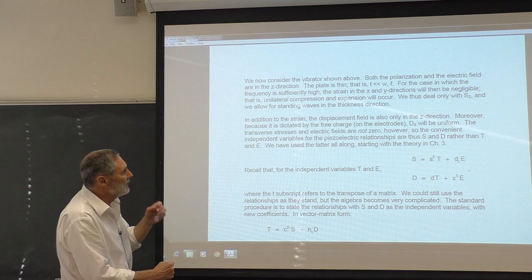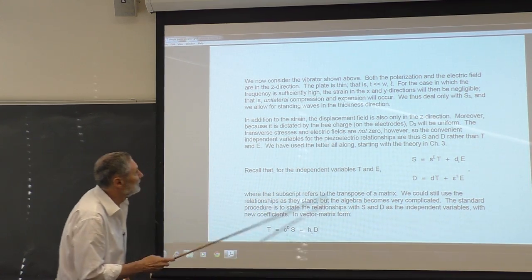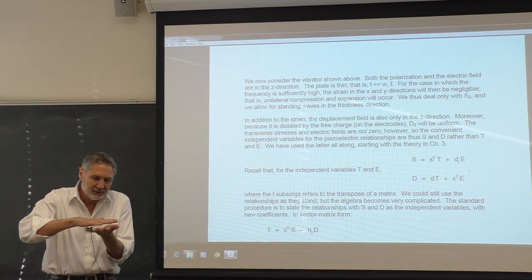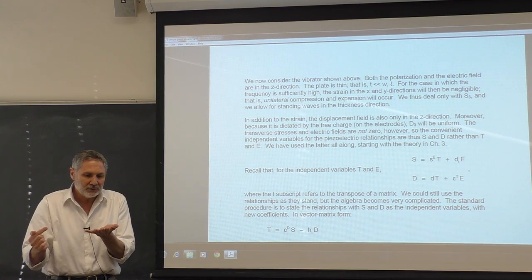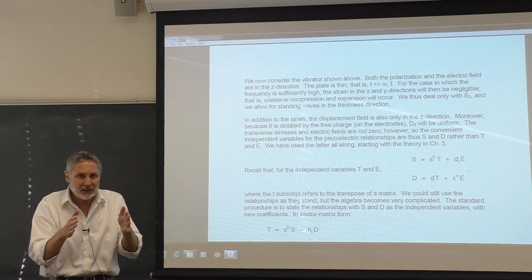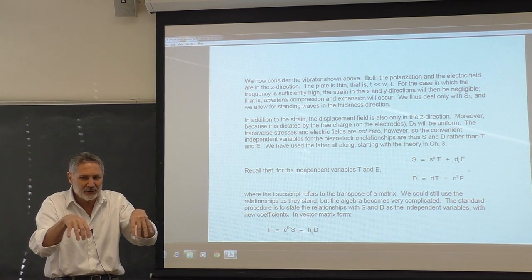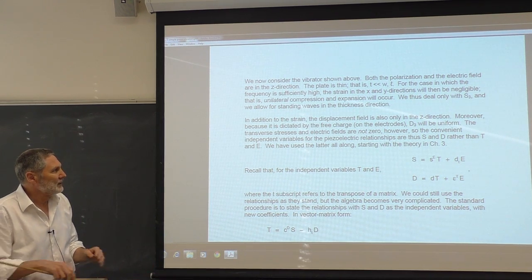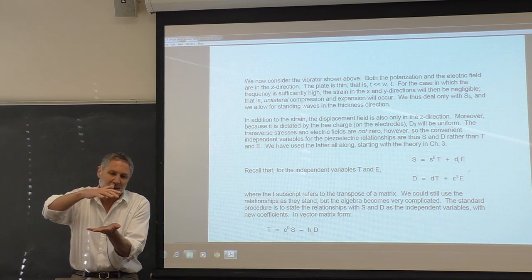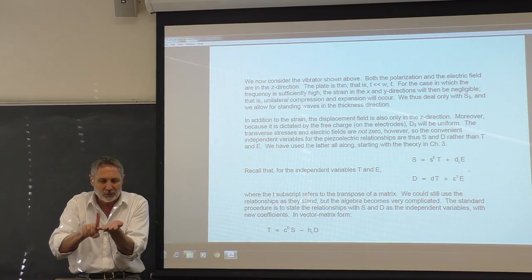Okay. Not only would it be nice to deal with S, but look at the electrical side here. Electrically, there's this standing wave here. There's going to be some free charge. The free charge will be uniformly distributed. It's not like with a length expander bar. Remember, in the length expander bar, the free charge adjusted to keep the electric field constant. This is different. So now, the electric field is going to be complicated here. And we'll see this, but I might as well talk about it right now. When you have a standing wave in this direction, you have the polarization in there, right?